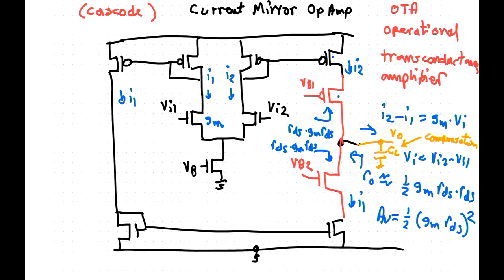In the OTA itself, the bottom current mirror can introduce what's called negative feedback to compensate the mismatch. You're thinking of a fully differential amplifier now. Yeah, but on a fully differential amplifier you have two nodes you've got to control, so you have a two-dimensional problem. One of them you can control with an equivalent input offset voltage that is fixed by the negative feedback. But if you have two nodes, you only have one loop there. You've got to have another loop to control the other dimension.